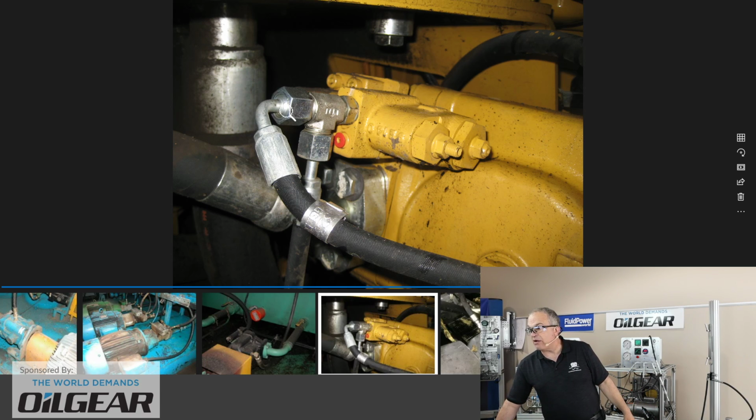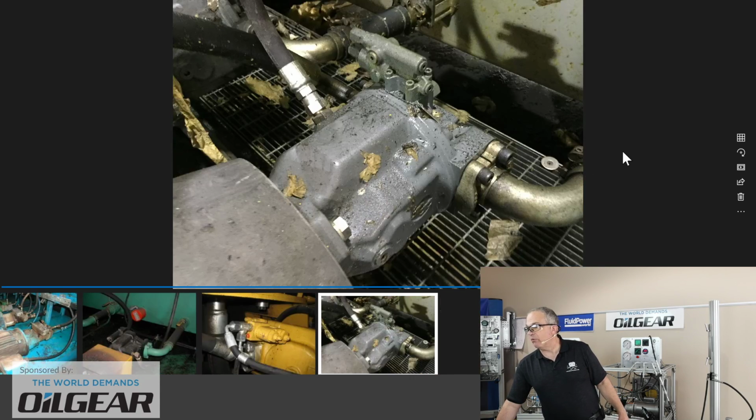But you may have that control hose coming in, and so you will have to look into your machinery maintenance and adjustment notes to find out what you need to do to knock out the effect of the lower flow compensator, the load sense compensator, in order to allow you to adjust the pressure compensator. Or join us in August and we'll cover that one at that point.